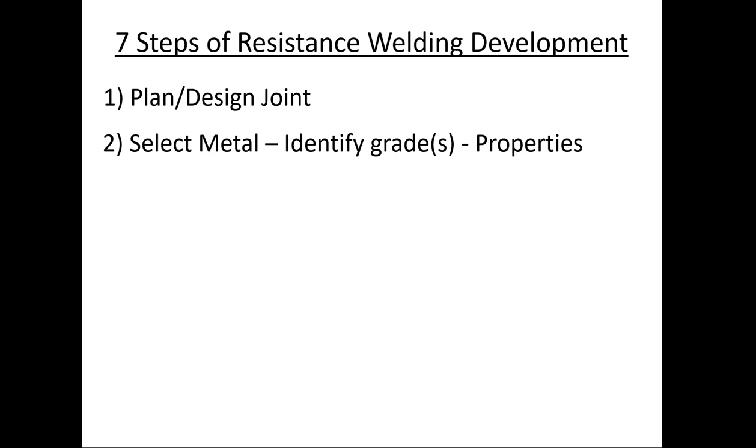Most of the time, it's pretty simple what we're doing with resistance welding. The easiest metals to weld, by the way, are the stainless steels or the nickel-based materials, or high nickel materials. Nickel is very resistant, so it absolutely loves resistance welding. I've personally seen 30 layers of material, thin, thick, all kinds, and it actually resistance welded right through the whole stack that we did at Bombardier years ago.